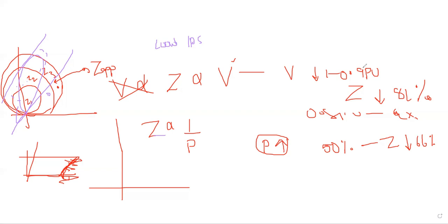But by considering both load encroachment and power swings, we have to ensure that the relay should not operate under these conditions. That can be achieved by three considerations. One is the quadratic characteristic. The other one is going with a lenticular characteristic. Otherwise, in the olden days, they were using blinders also.